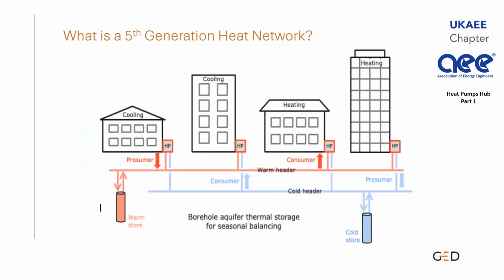So moving on from fourth generation to fifth generation, what is a fifth generation heat network? Fundamentally, we're using an ambient heat loop. So this is energy from nature running at anywhere between 0 and 20 degrees centigrade from water, boreholes, waste heat being distributed to buildings in uninsulated pipe. And each building has its own heat pump. So Dave has spoken about the centralized heat pump delivering out high-grade heat. In this situation, we're looking at ambient heat, and a single network can offer both heating and cooling opportunities to individual buildings. And that network can run between 10 and 20 degrees.